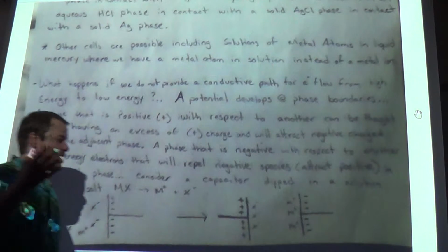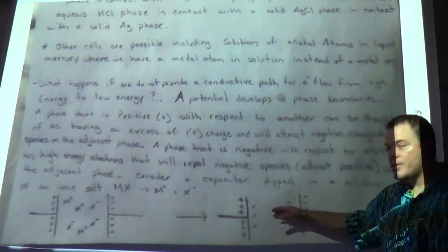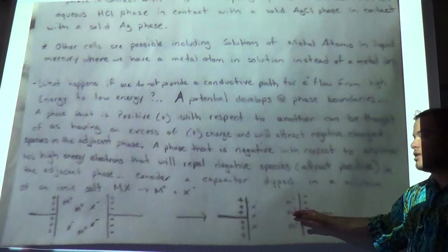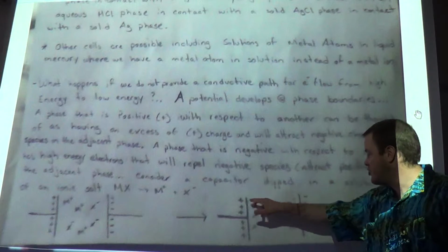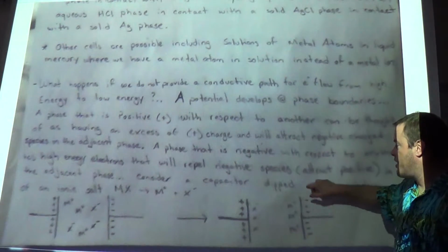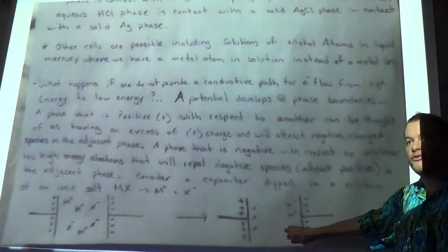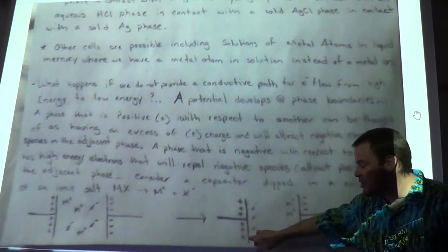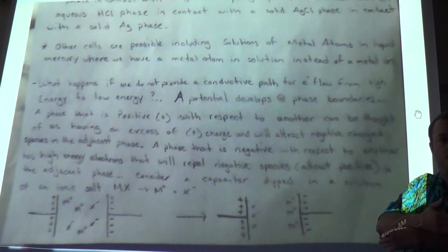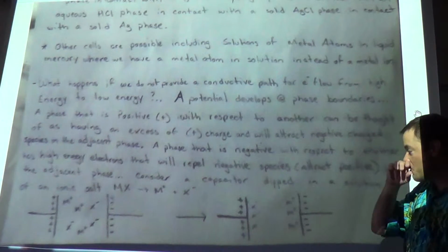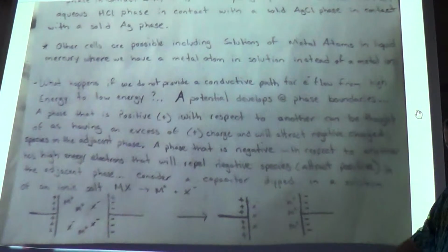So these ions will move, like we saw, and they'll try to essentially neutralize the potential that they feel by setting up a counter potential. You'll notice that on the capacitor, we've got positive charge and negative charge. That'll result in a field vector that points in one direction. In the solution, we've got negative charge over here and positive charge over here. This results in a field vector that points in the opposite direction. And the two field vectors together tend to cancel out the total field. They tend to minimize the total field. So the solution acts to push against the push that it's being pushed on with.